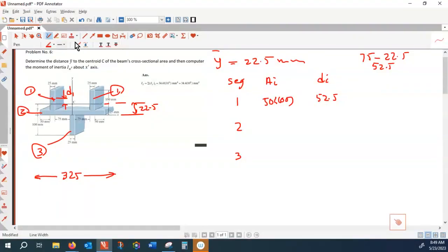And then the next quantity we want to calculate is the moment of inertia from the table for the first shape. Let's call this x prime. That is 1/12 BH cubed. Because there are two of them, B is 25 plus 25, that is 50, and H is 100, so that is 100 cubed.